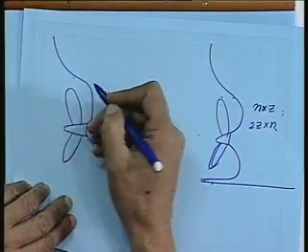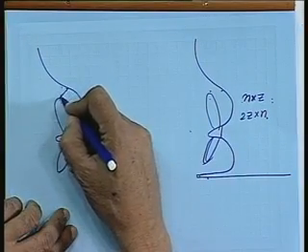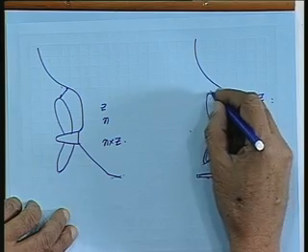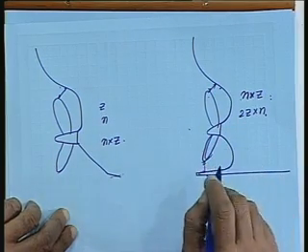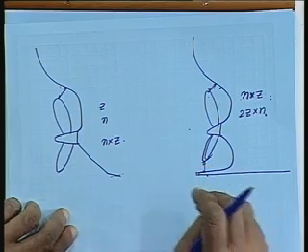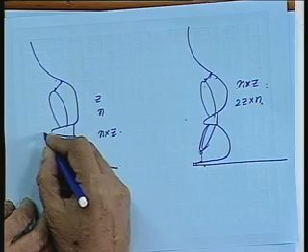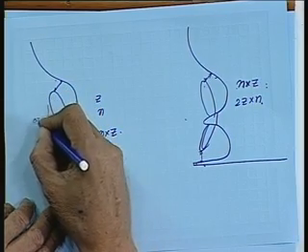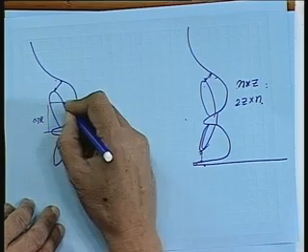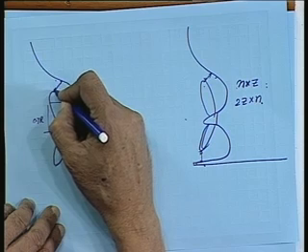Now, if we want to get the effect less, then there has to be some sort of a minimum distance kept between this tip here and these pieces here. You will see that the rules will tell you that at 0.7 R, what should be the minimum clearance given here, and what should be the minimum tip clearance given here?